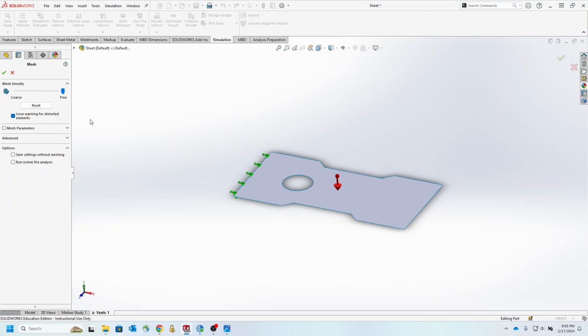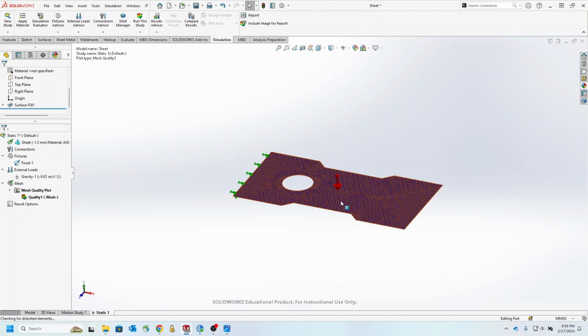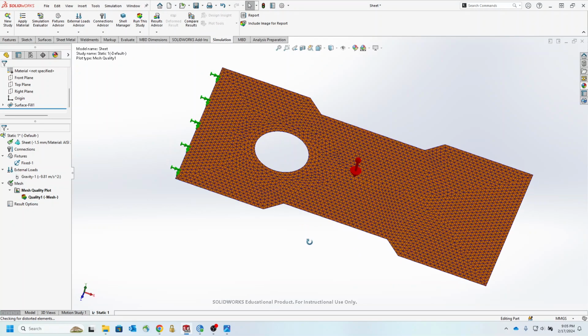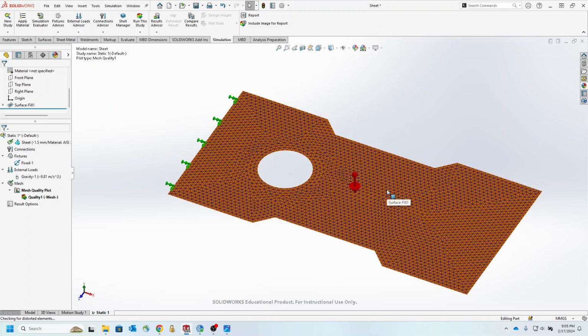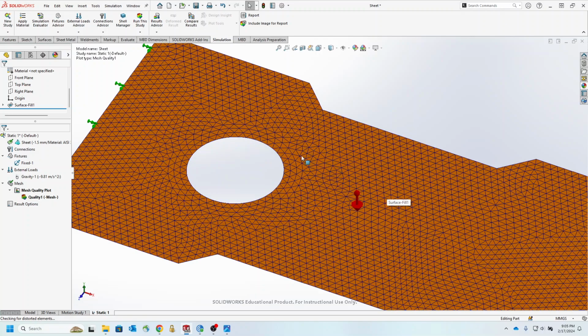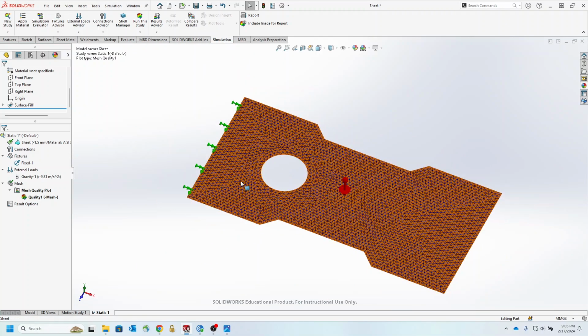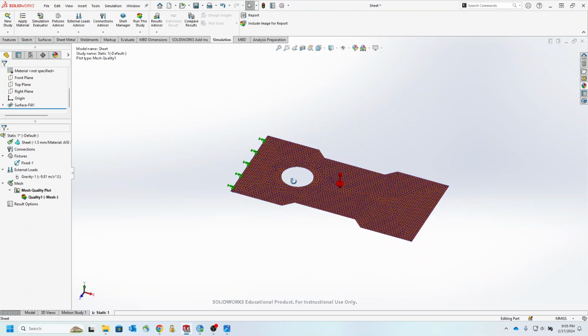So I can drag it all the way to fine, and when I select it here to define a mesh, I can have a very good mesh, and the time was very small compared to defining it with respect to a solid body. And now you see that around this edge, the geometry is really adapting how to define the mesh.